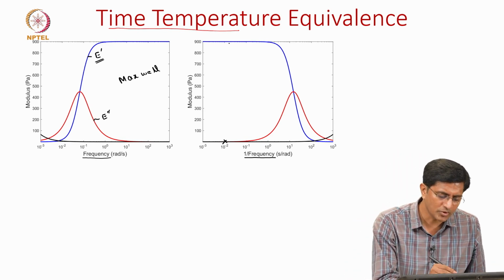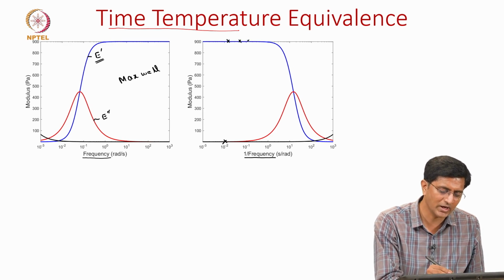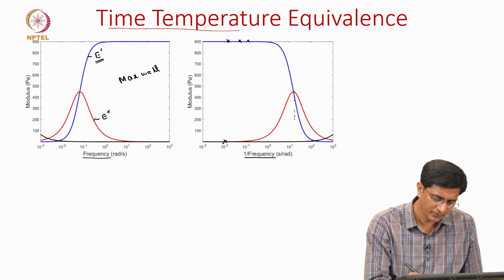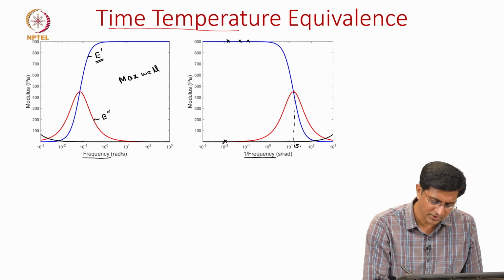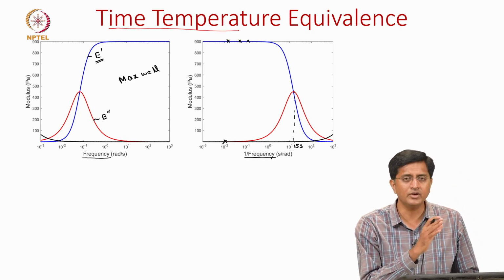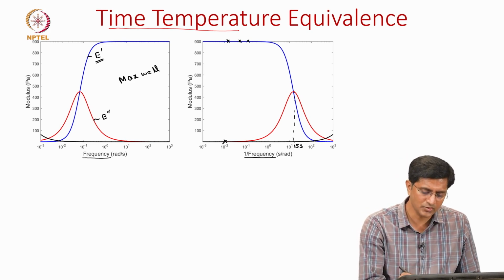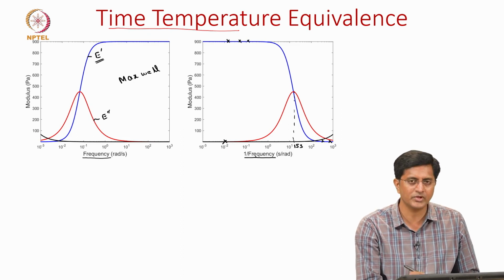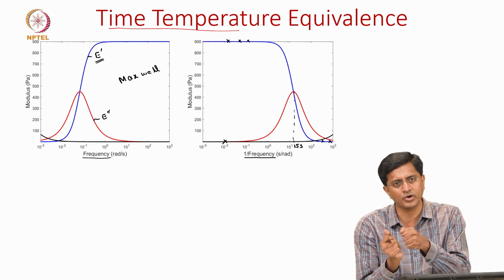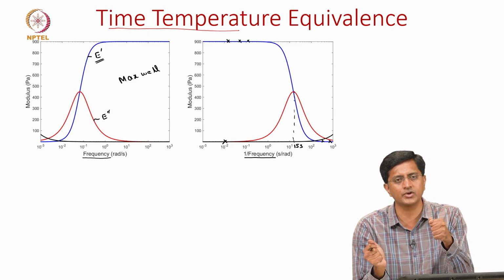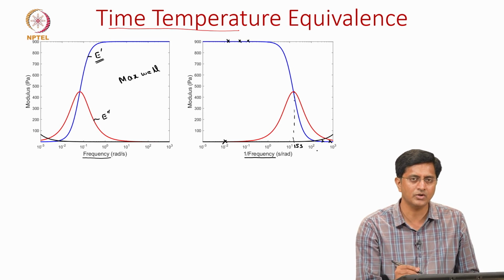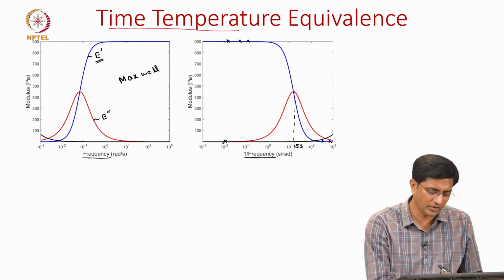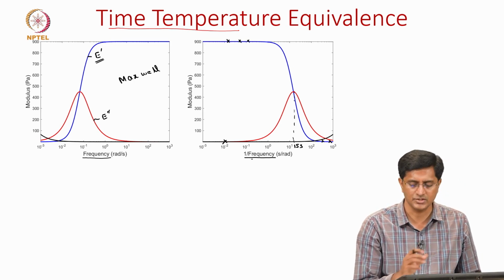So, mostly the modulus values are high, but as you increase these times and reach the relaxation time, which in this case is 15 seconds, that is when it goes from very high modulus values to very low modulus values. So, again at very high values of 1 by frequency, or otherwise a very slow test where you give enough time for it to deform, the modulus values are low. Okay. So, we have shown that between frequency and 1 by frequency the trend of the curve changes.